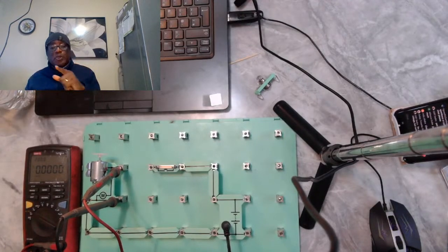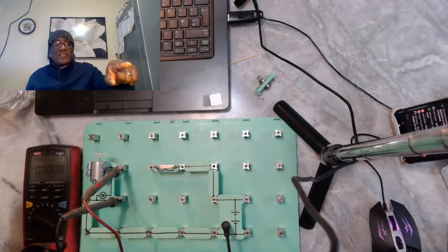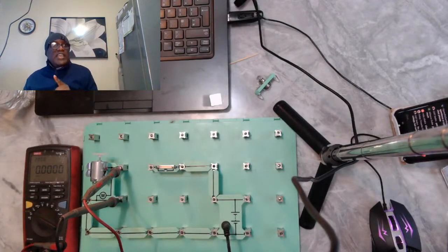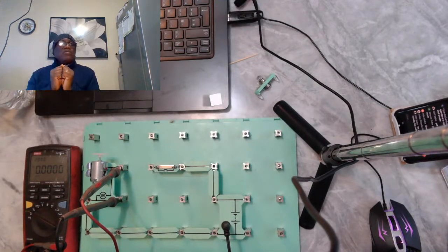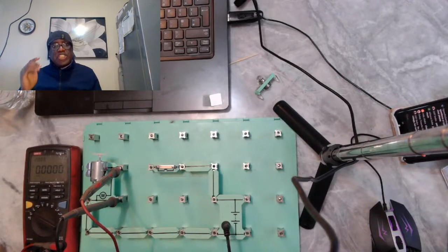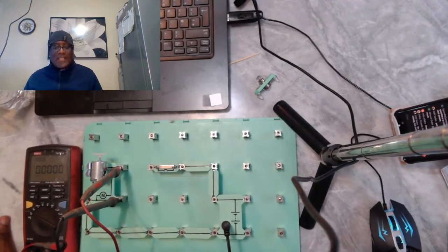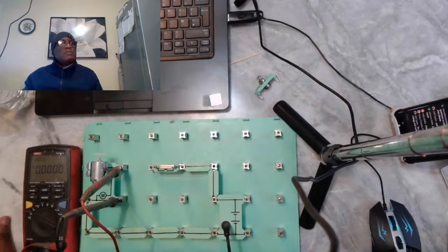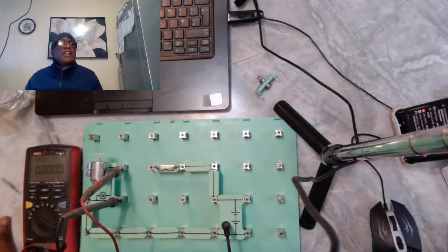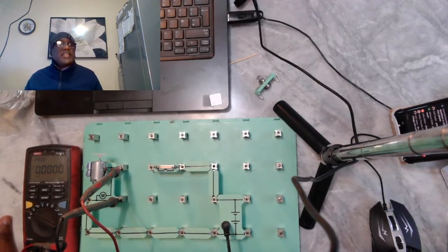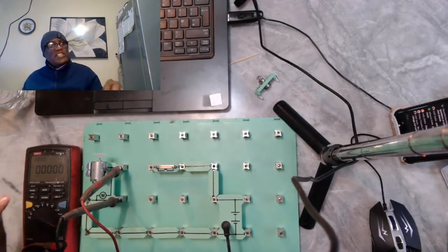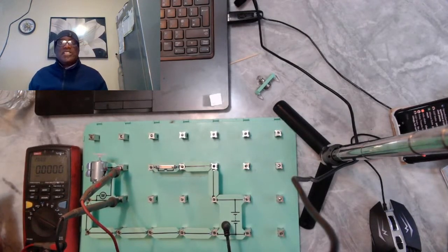It's important for you to know where your power starts and where it ends, where your ground starts and where it ends. So you go to the ground side and then you check for voltage. You are looking for voltage on the ground side. So the switch is on, and then you go on the ground side or on the positive side and look for voltage. The side that is going to have voltage is the side that you want to investigate for an open.